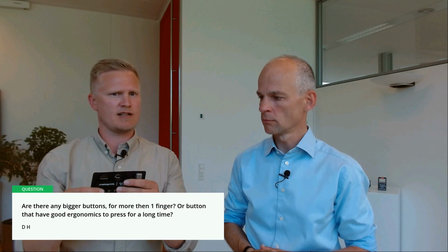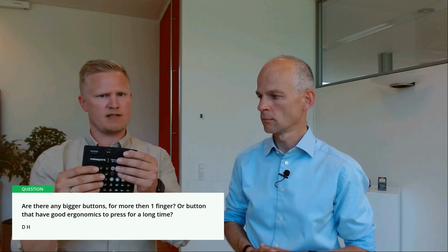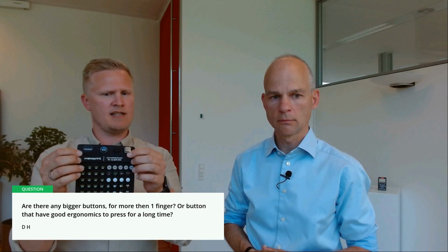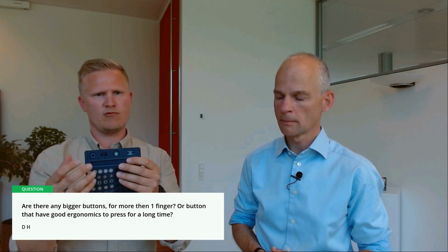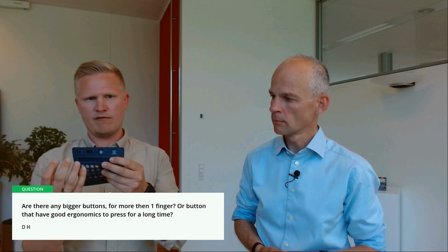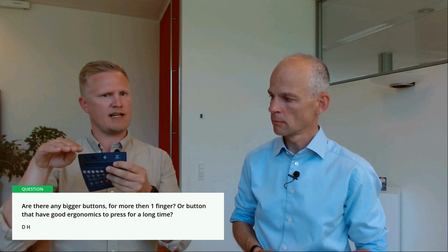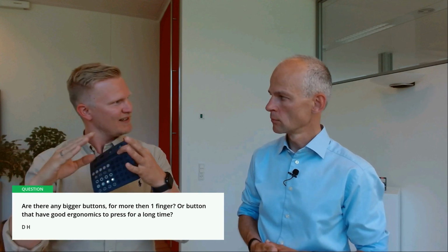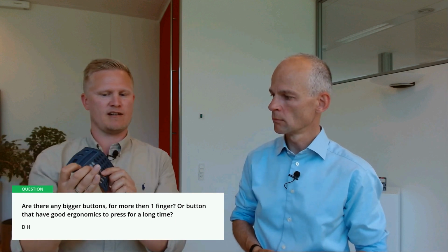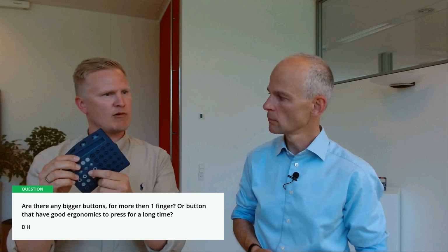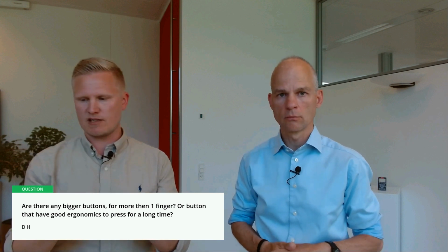If it's for a silicon keypad, you have a bit more possibilities to do an elongated key where you can support it underneath, maybe to actually do a base in the silicon design underneath to support it. So you get a feeling that it's an even distribution of the force you're applying, but the activation point underneath could be one or more carbon pills directly onto a PCB.